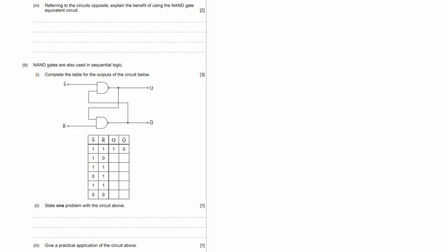The next one, look, notice R has gone low. R has gone low there. So Q should change. So Q should be reset. Nothing happens on that third one down because R or S hasn't changed. This next one, S has gone low, so we set because S has gone low. Nothing happens on the next one.